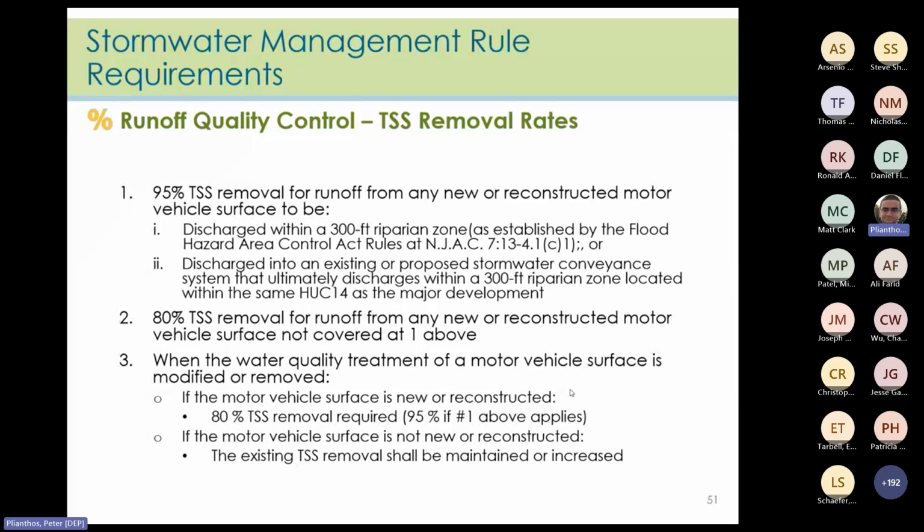And then under number 3, when the water quality treatment of a motor vehicle surface is modified or removed, if the motor vehicle surface is new or reconstructed, then 80% TSS removal would be required, or 95% TSS removal would be required if number 1 above applies. And then if the motor vehicle surface is not new or reconstructed, the existing TSS removal shall be maintained or increased.